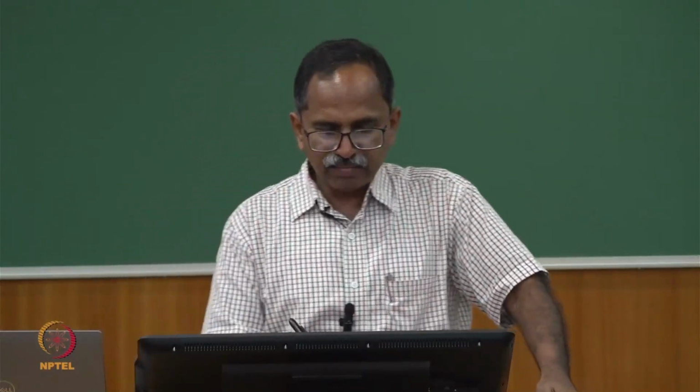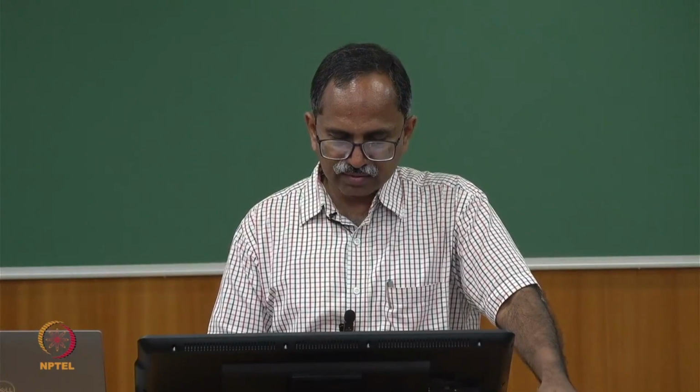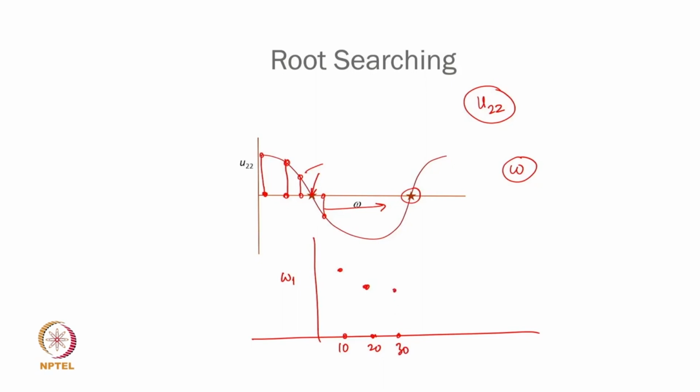Now what can be done by you is that same system, if you discretize it into, let's say, 10 segments, find out what omega 1 is. Maybe you will get omega 1 as this. Then instead of 10 segments, that entire gearbox you discretize into 20 segments. Reevaluate omega 1. Maybe you will get this value. Discretize into 25, 30 elements. You will find that with a larger number of segments, this omega 1 will stabilize and will approach a constant value.